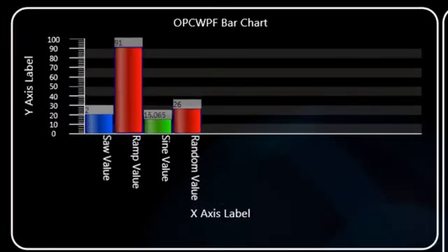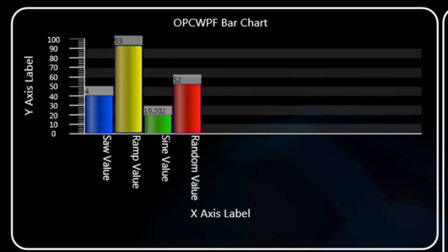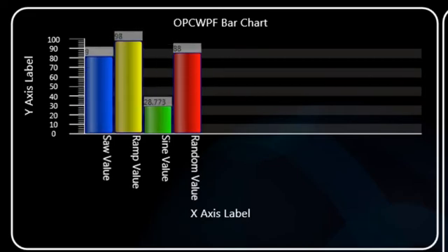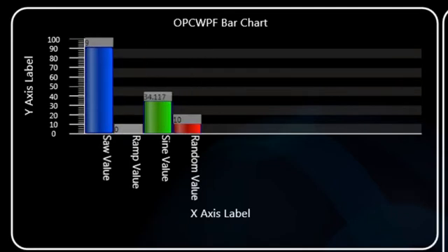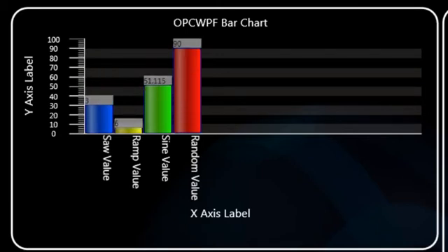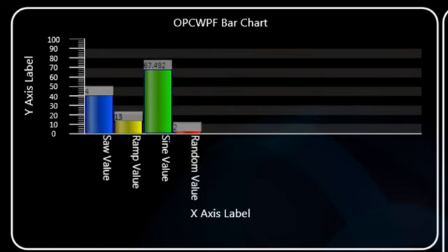The bar chart allows for a single side-by-side view of multiple live data points in a bar chart style. Each bar can be set to absolute scale or percent of range. Each bar can also have its own gain and offset. There are multiple properties that can be controlled by live data from your OPC system service, such as title, bar color, flashing, and others.